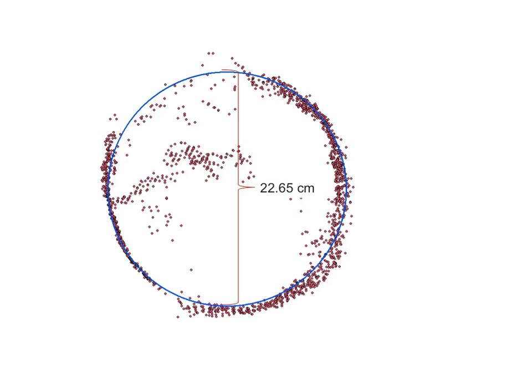Zoomed into one of those areas, this is what that cookie or that profile view of that slice would look like, right? And you can see that there's a little bit of noise in there, but roughly we've captured the shape of that pole. So with some GIS magic, we can fit a circle into that collection of points. And as I was doing this, I was making sure that every step I did, I could do in an automated fashion. So if I had to do 1,000 of these or 10 of them, it would take the same amount of effort for me. I could just give it to the programmer and let it spit this out. Then we can calculate our diameter from that collection of points.